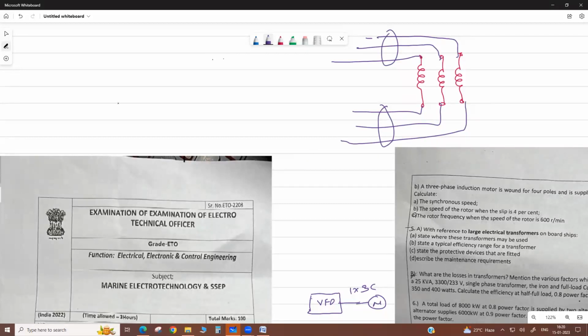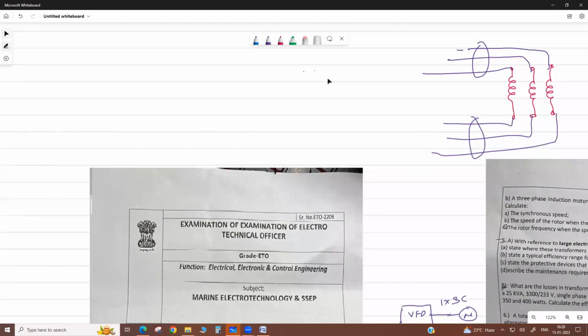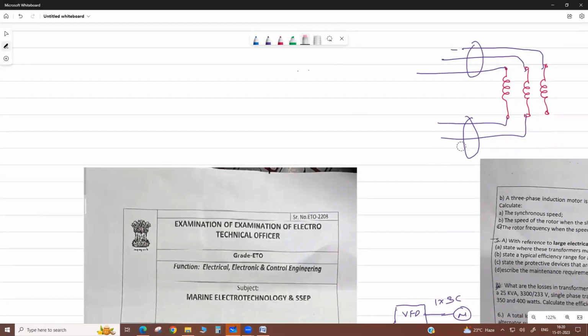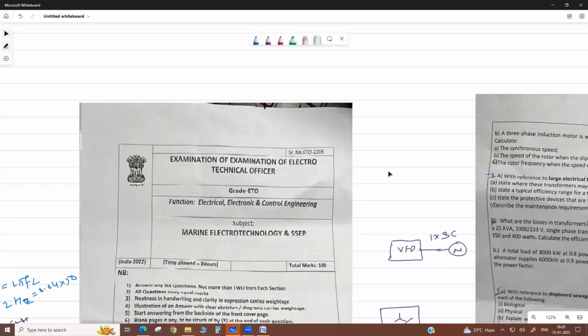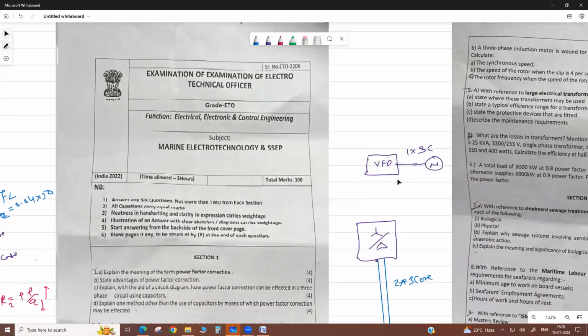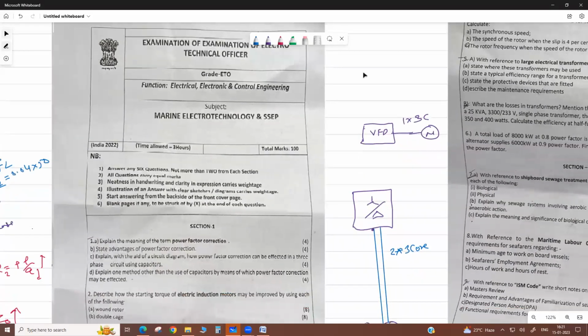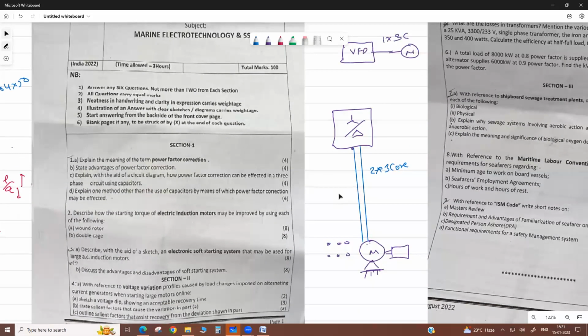Now, if you look practically, if one motor is connected to a star delta starter, there will be 2 cables. Now in VFD, DOL starter and soft starter, only a single run of cable is there. So this is also a disadvantage of star delta, because you have the cable cost, installation and termination.